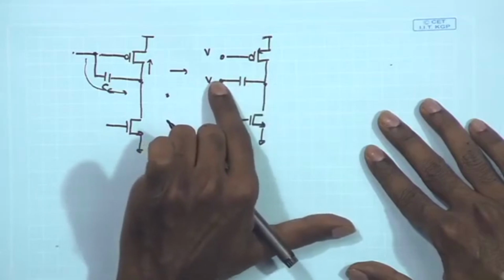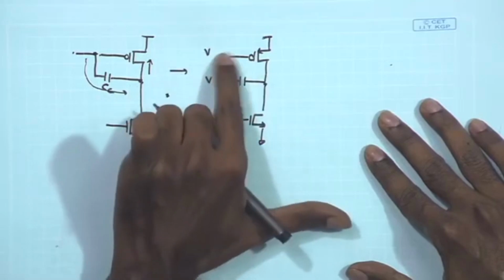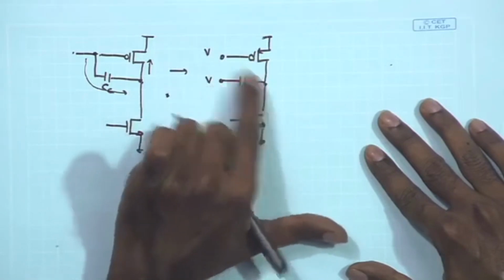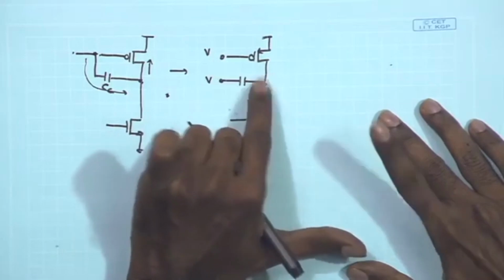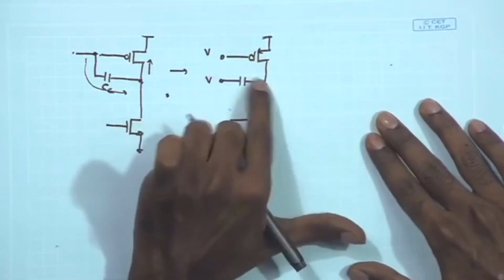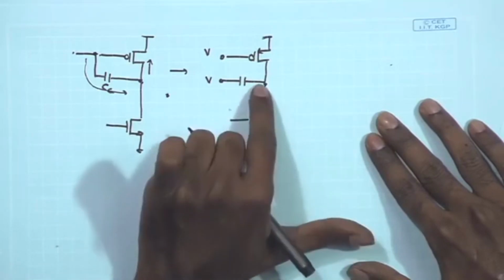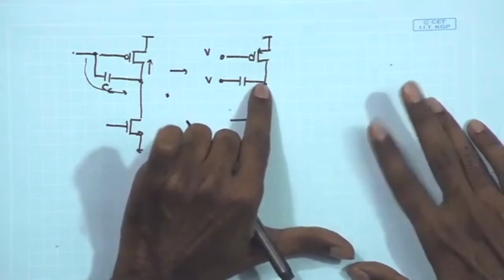If at some frequencies the signals provided by these two paths have exact cancellation, because of a 180-degree phase shift in one and relatively positive phase in the other, these two signals can combine destructively.